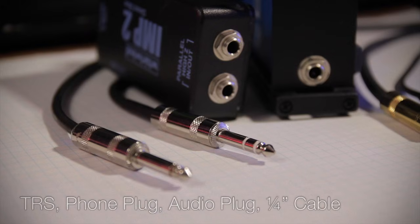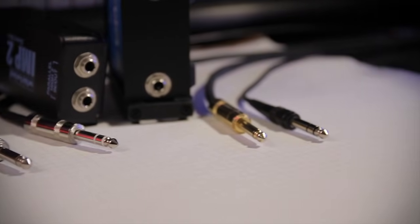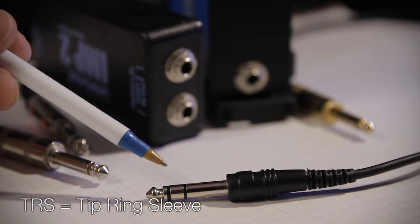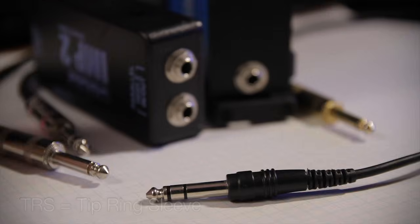This connection has many names like TRS, phone plug, audio plug, quarter-inch cable. It was invented for use in the telephone switchboards in the 20th century and is still widely used today in both its original quarter-inch size and miniaturized versions, 3.5 millimeter or approximately 1/8 inch, and 2.5 millimeter, approximately 3/32 inch. The connector's name is an initialism derived from the names of the 3 conducting parts of the plug, the tip, ring, and sleeve, hence TRS.